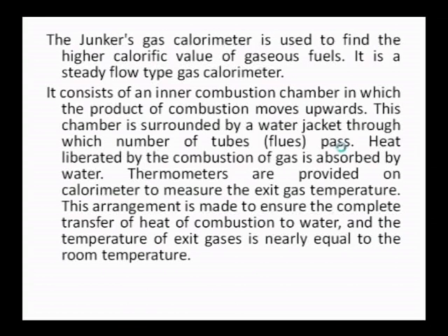The main intention of the flow of the gases here is to transfer the heat to the surrounding water. Thermometers are provided on the calorimeter to measure the exit gas temperature. This arrangement is made to ensure the complete transfer of heat of combustion to water.